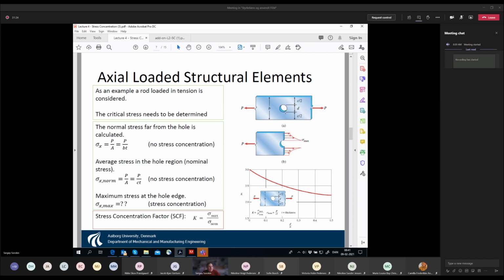So if you take this kind of crack, because now it will be looking more like a crack, you have the same width, but in this direction it's nothing. Then you have infinite stress concentration. And then if you have infinite stress concentration, then you're in big trouble, because no matter how small the force is, in this point you have infinitely large stresses, and you have a fracture.